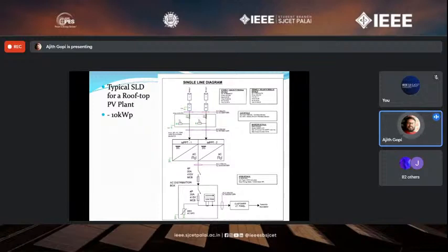For example, I told you about my solar rooftop. I have a lot of rooftop facing west. So I can connect all the solar panels on the west to MPPT1 and all the solar panels to the south to MPPT2. It won't make much problem. The earlier single MPPT inverter cannot work here. So if I have a multiple MPPT inverter, then I can connect solar PV modules of different orientations and characteristics to my inverter.